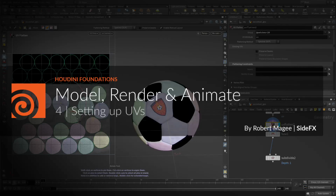Welcome to part 4. We're going to set up some UVs on the soccer ball for texturing purposes. In order to set up materials and textures, it's important to make sure that there are proper UVs set up on your object. Geometry in Houdini does not come with UVs by default, therefore you must create them yourself.